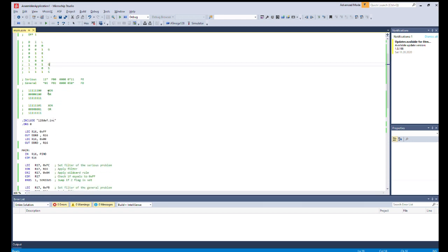Let's move to the core process itself. We identify a serious problem if, according to our DIL, it's 1-1 and then the wildcard. So the door is open, ignition is on, and it doesn't matter what lights are. All of that we output to the zero pin of the port B. So we have to apply this type of filter, which in complement results in FE in hexadecimal format.